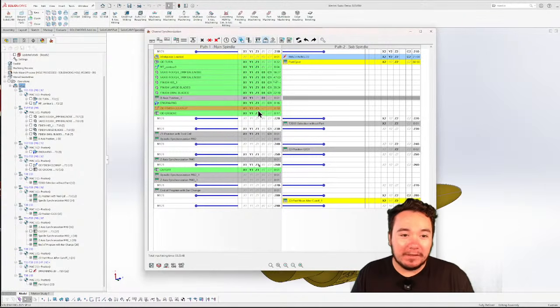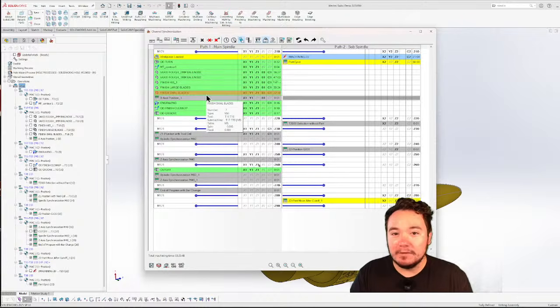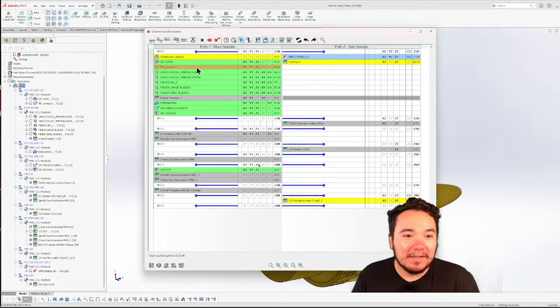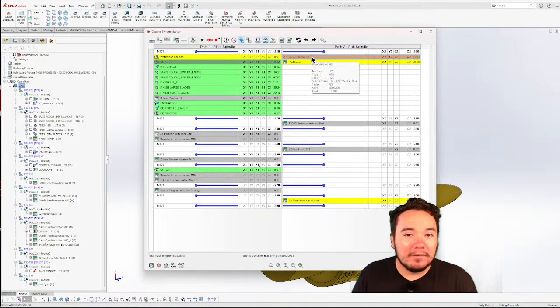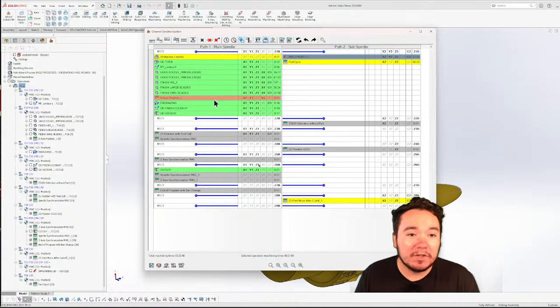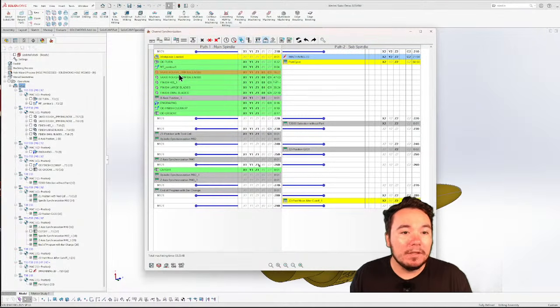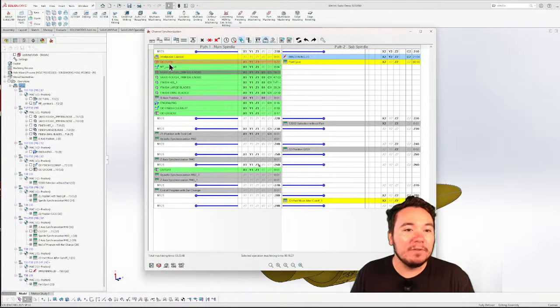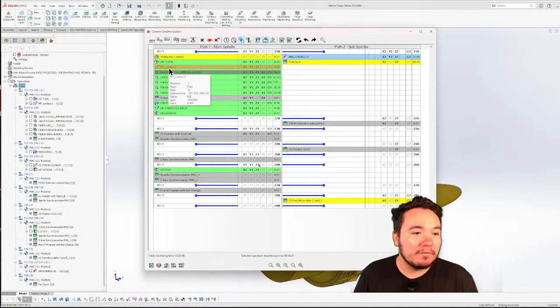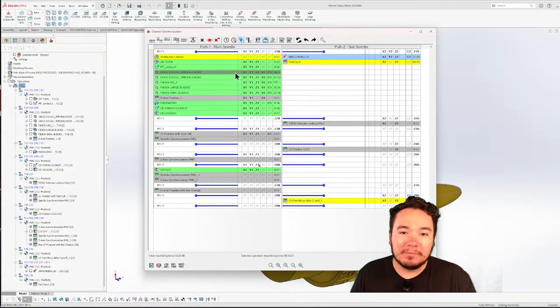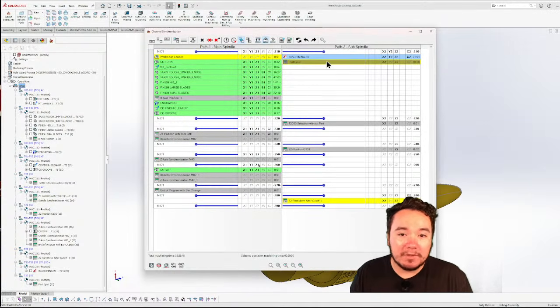So right there, we have synchronous cutting happening at the same time. The OD turn will happen at the same time as iMachining, and whenever the iMachining finishes, maybe in the middle of this 5-axis rough, which would probably happen because the OD turn and the manual turn, which is the finish, happen pretty dang quick. So it'll probably finish then.